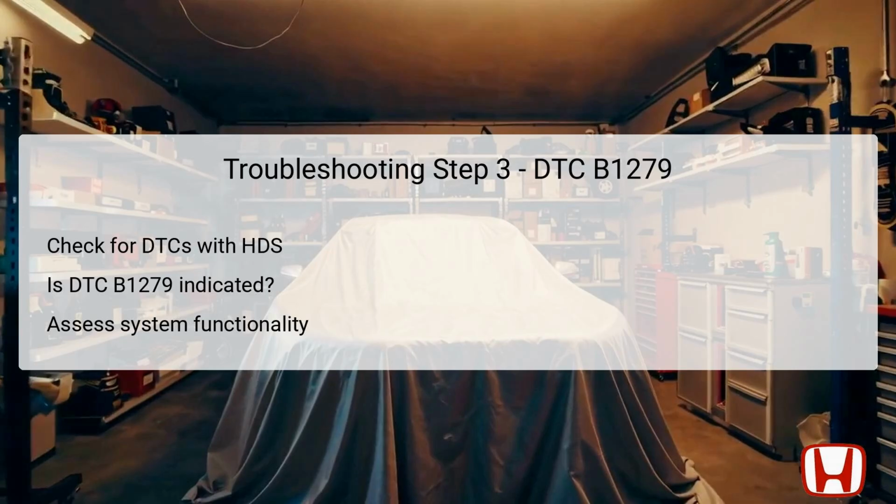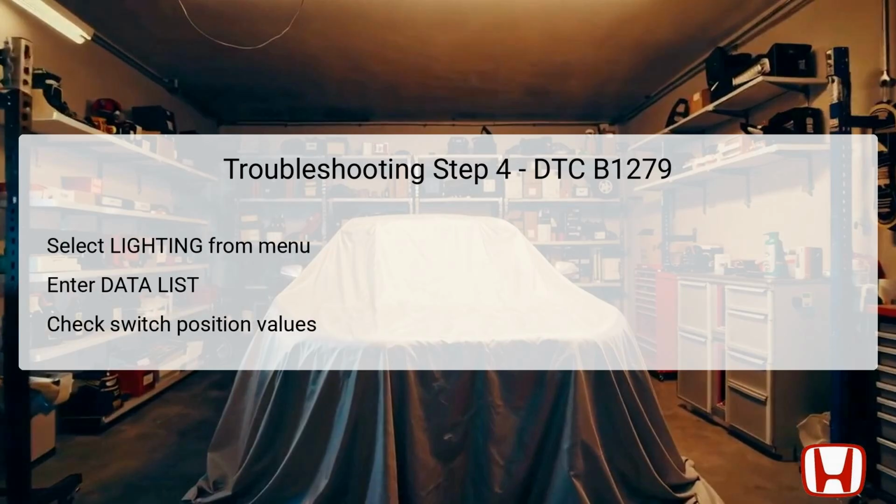This assessment helps solidify the reliability of the dimmer switch circuit and identify potential issues with connectivity. In this step, the next action is to select the lighting option from the Body Electrical System Select menu in the HDS. By entering the data list, you can begin to assess the readings and operational status of the combination light switch. It is crucial to check each position value presented in the data list, as it indicates how the switch is functioning when operated.